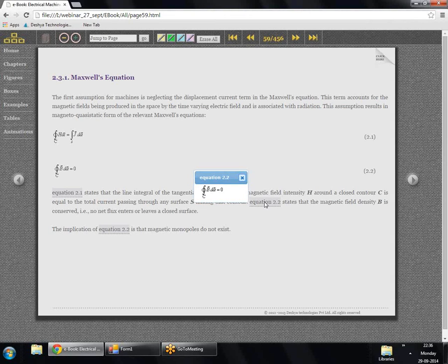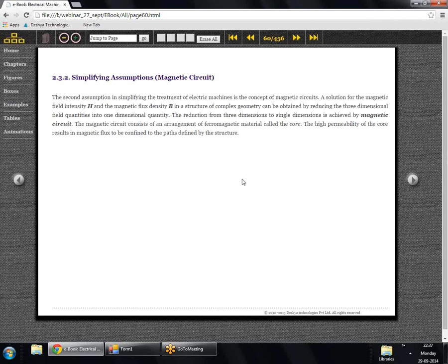This is a very important thing because if we look carefully, we do not have rotating electrical machines with 3, 5, 7 or 9 poles. The machines are always with an even number of poles. So an electrical motor might have 2 poles, 4 poles, 6 poles, 8 poles, but it can never have 3 poles or 5 poles, because magnetic monopoles do not exist, as governed by equation 2.2. This is a very fundamental thing which we have to keep in mind.